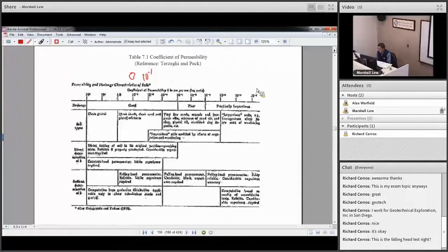He was interested in how water flows through soil, and he set up an apparatus with a soil sample where he flowed water through it while maintaining a constant head. He probably was out there pouring water in as it was dropping, trying to keep the water level constant. Then he measured the amount of flow through the soil after it reached a steady state.